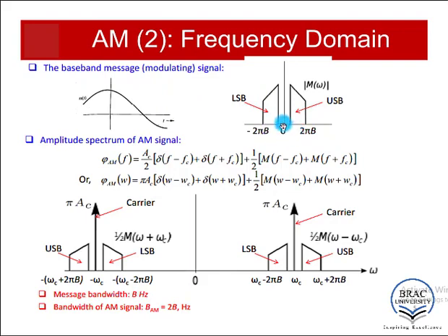Now when you are modulating with a cos wave, this whole spectrum is shifted by omega c in the right direction. You can see that M(omega minus omega c). So the whole spectrum now gets shifted from 0 center frequency to omega c center frequency. Here you can see the same two trapezoidal shapes distributed around omega c frequency, right?